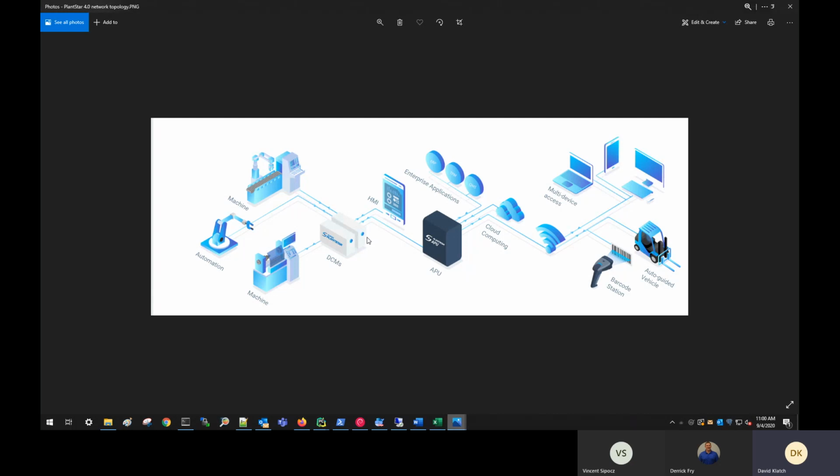That's different from that reboot, because when you reboot this DCM, it keeps its database the way it was, and it just pulls in new data. So let's say the database has 5 gigs worth of data on it, and you reboot that 5 gig, it stays the way it is. But if the APU had some more information, another half a gig that was relevant to the DCM, then it would pull in that information, update basically.